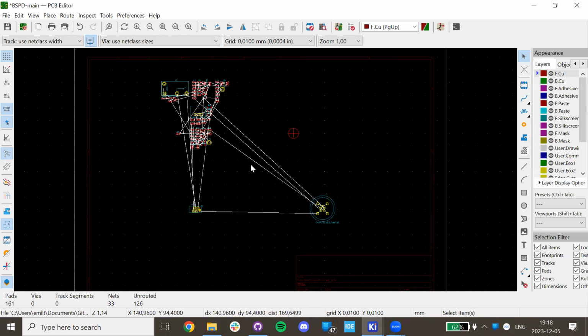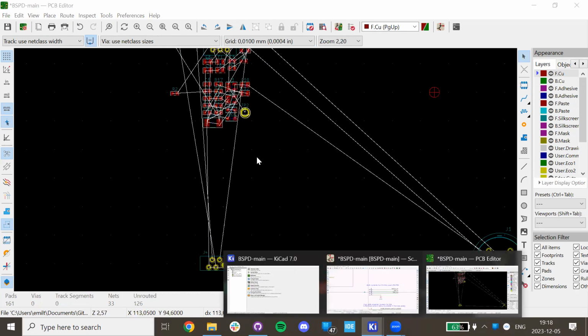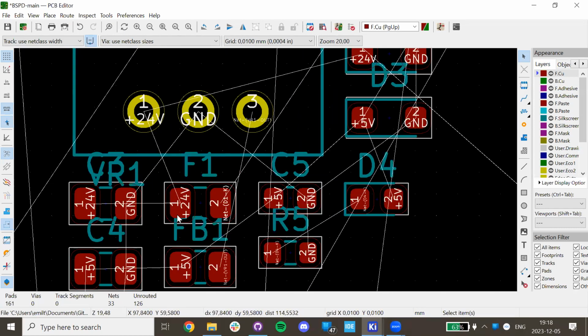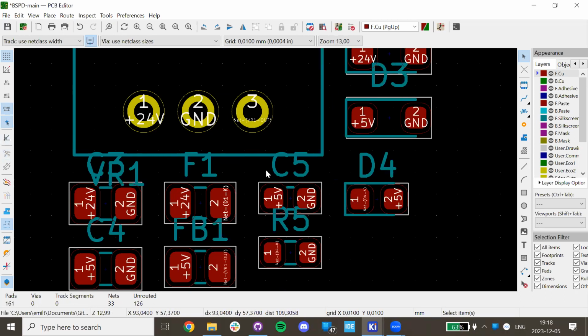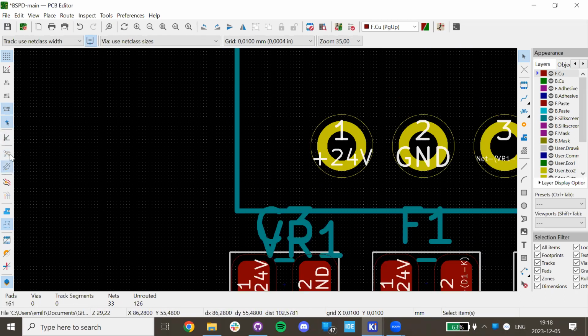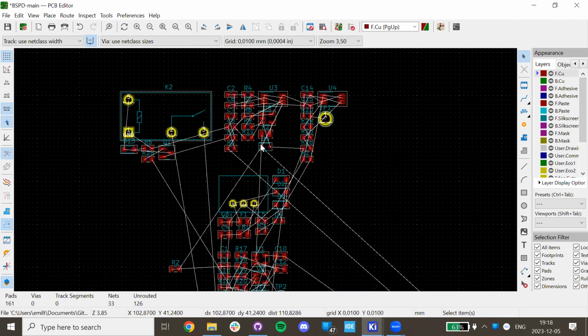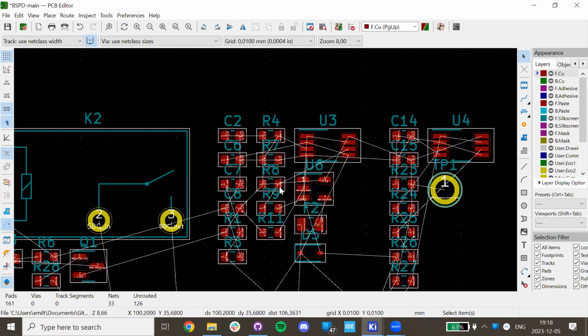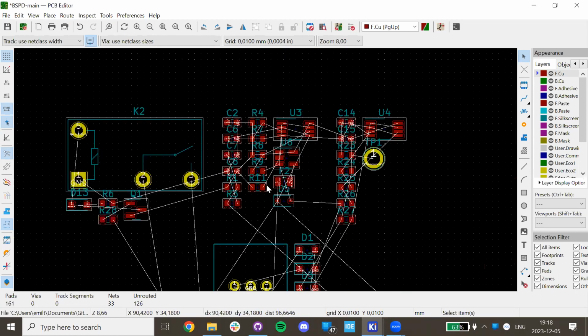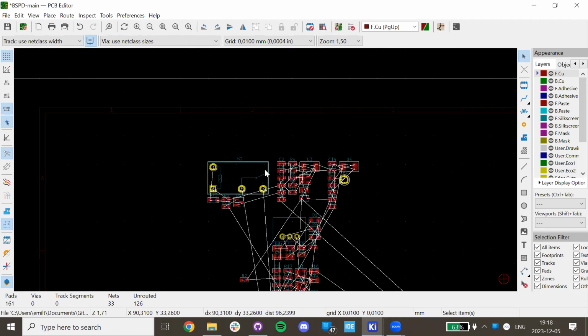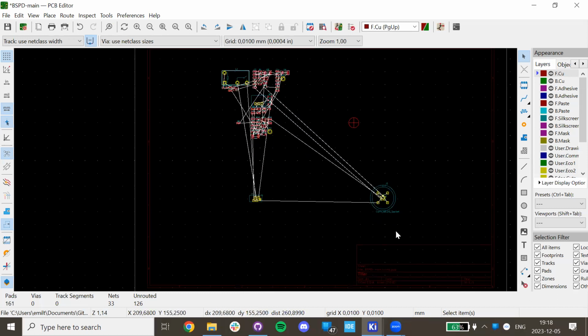Perfect. So we said we wanted to make this PCB small. Well, there are several ways to start. You see these white lines? These white lines are indicating what should be connected where. You can remove them if you want, but it's showing you what items are linked together. So these give you some idea. You see that there's a lot of interconnecting lines here. So these give you some idea that this component should probably be pretty close to make the routing of the traces easier. And now that we're saying, okay, we're making a small PCB, I have a trick that I like to do.